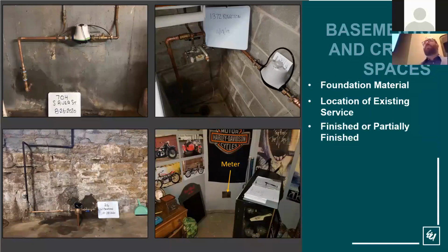Some of the challenges involved with basements, you're going to have different foundation material walls. Some of the walls are going to be made of concrete, some of them CMU, some of them are going to be stone. And the good news is that all of these materials can be directionally drilled through to replace a service, but you may want to have some special considerations for particularly fragile foundations that you encounter.